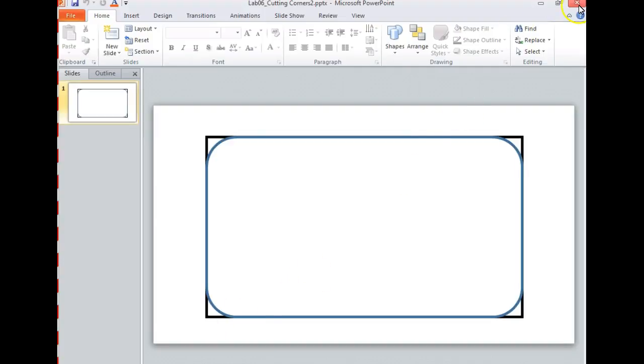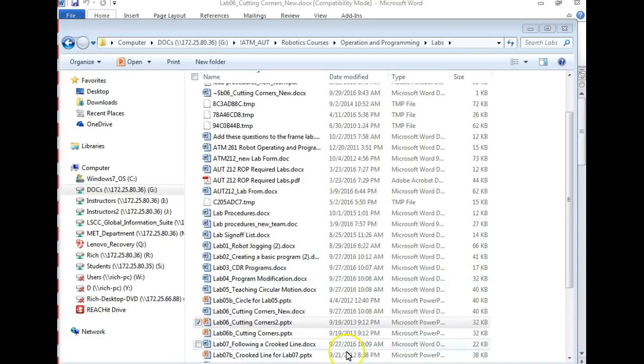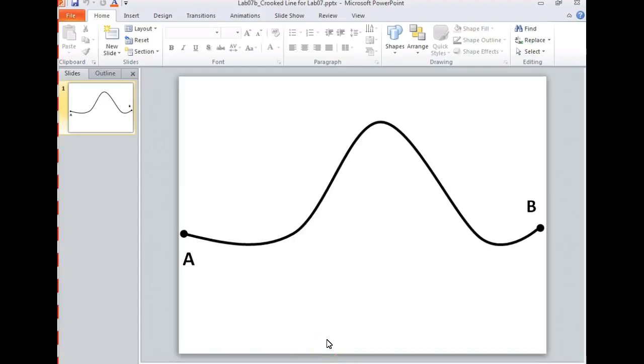And then hopefully, if y'all get this far, the next one is this guy right here. So what we do is we make it follow that line right there. But we only got 3 moves, right? But between circular moves and linear moves and joint moves and round offs, you can make this robot follow any path you want it to follow. You strictly can. So hopefully y'all get that far.